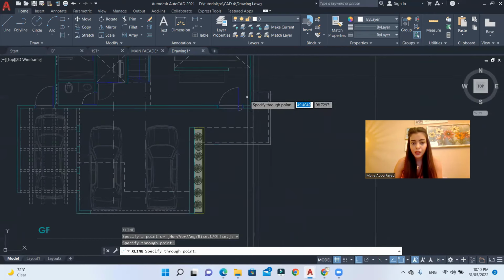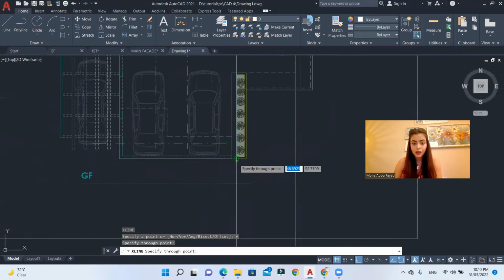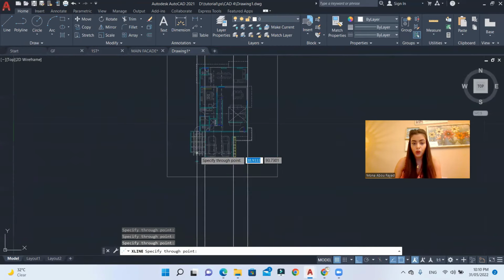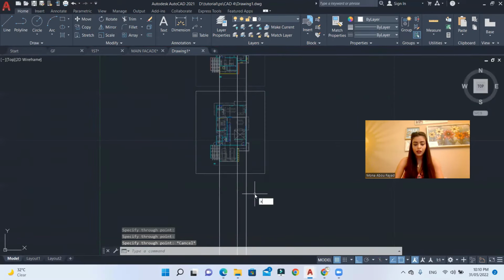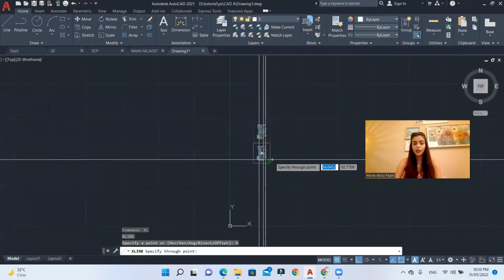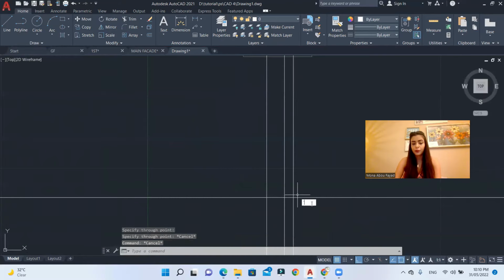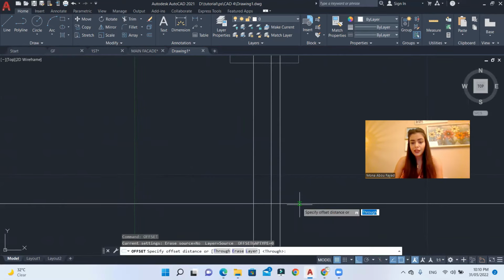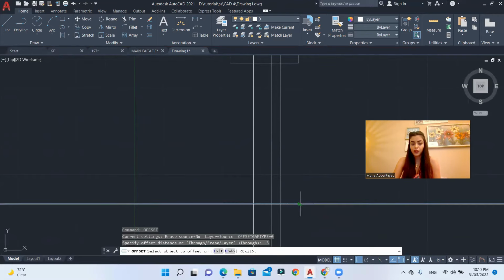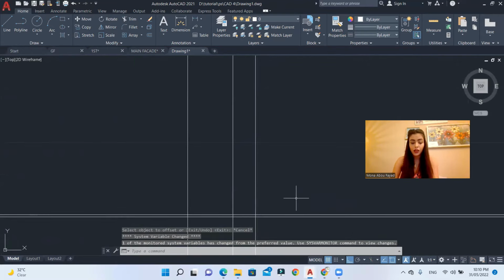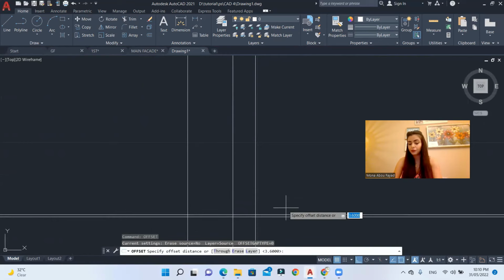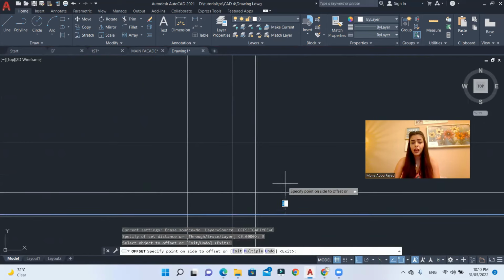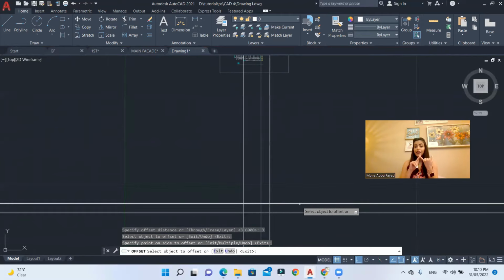So for that, you can just start selecting the walls from here, and then you can go back and select horizontal lines to define your slab. And then you can just start offsetting. Offset, like, what is the slab? Is it 0.3 meters? You can just offset 0.3. And then what is the clear height? You can offset, like, let's say 3 meters, and so on. This is very functional in the sections and in the elevations.